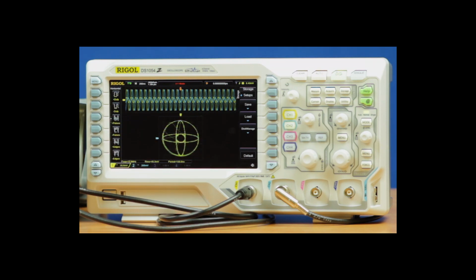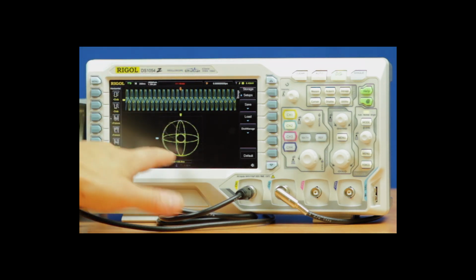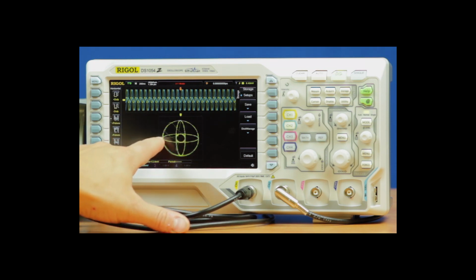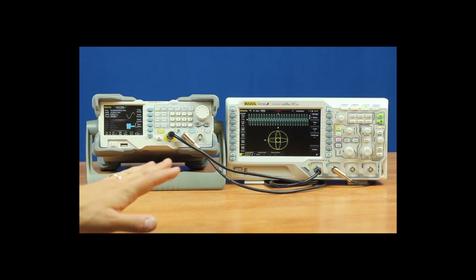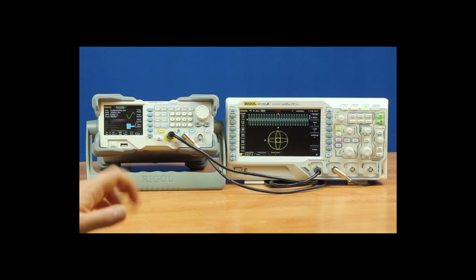Another way to verify that these signals are 90 degrees out of phase is if we look down the center line of channel 1, we can see that when channel 1 is 0, channel 2 is always very high or low. When channel 2 is 0, channel 1 is high or low. So this really indicates you can see clearly it's 90 degrees out of phase, and we're able to look at the two amplitude rings as well. So this is different than a constellation diagram, but it is another way to visualize a phase difference using an oscilloscope in XY mode.